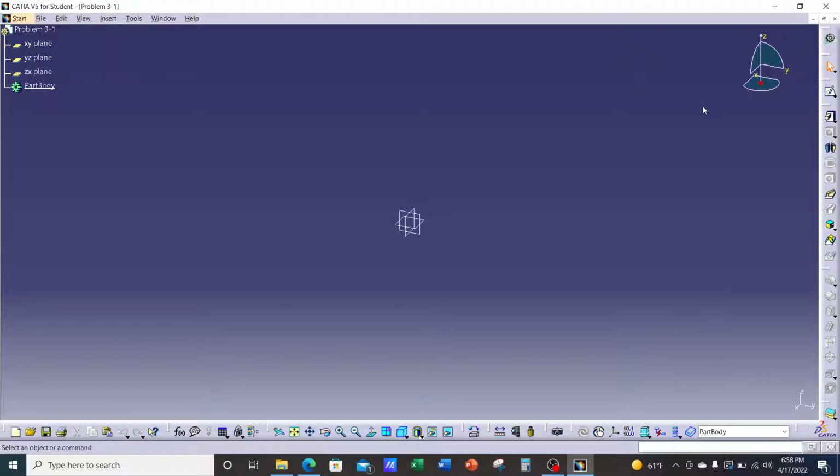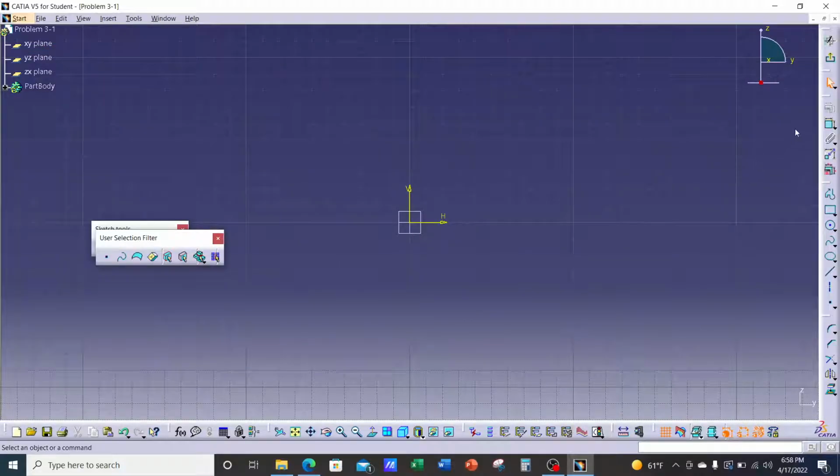All right, so let's go back to CATIA. So we're going to create a sketch. Once you click on sketch, you're going to see the part design workbench change to Sketcher. So I click on sketch, pick a plane. I'm going to pick the YZ plane. You can pick whichever plane you want. I'll pick the YZ plane, the second one on the list. Click. And I want you to notice that now we are in Sketcher. You can always hit the yellow arrow pointing upward to exit.